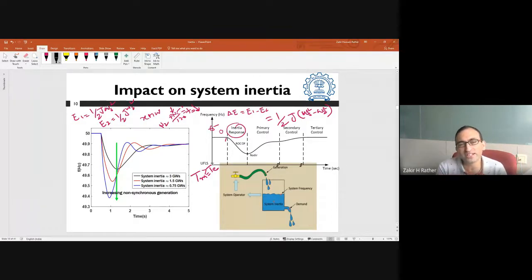Now, when you integrate renewables into the grid, you are displacing the conventional sources and diminishing the inertial power in the grid. Or if you talk of a new microgrid dominated primarily by renewable sources, you already have very low inertia to start with. And since you are in a dearth of inertia, you have a vulnerability of the frequency falling straight away to unacceptable values, where the protection of the grid has to get activated and a system blackout will take place.